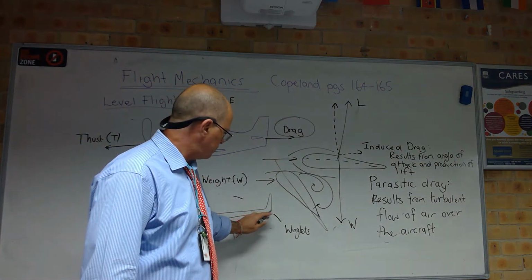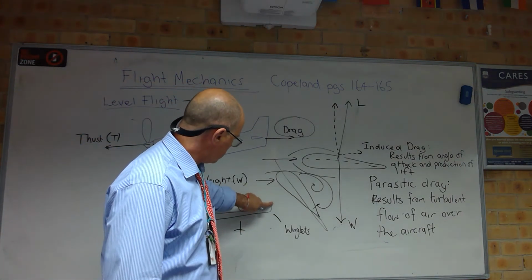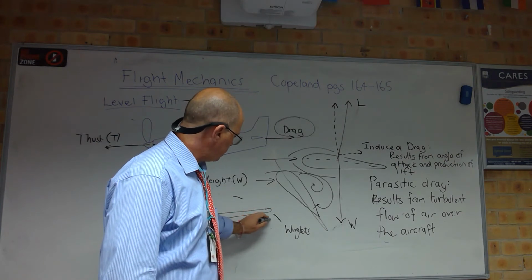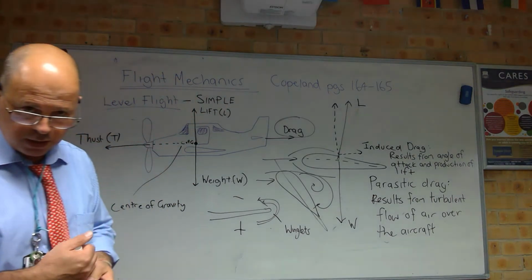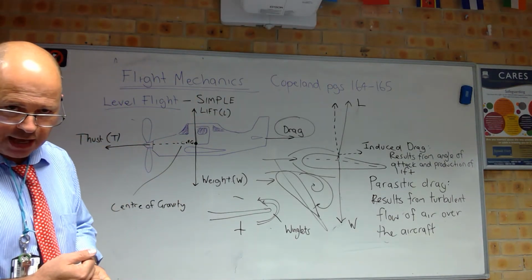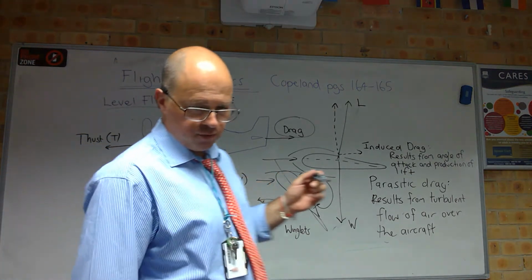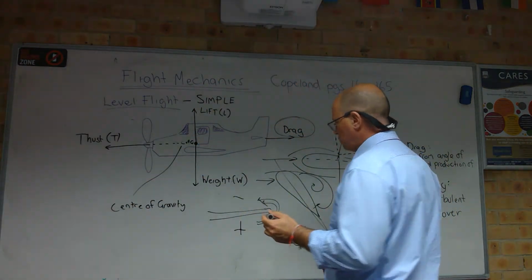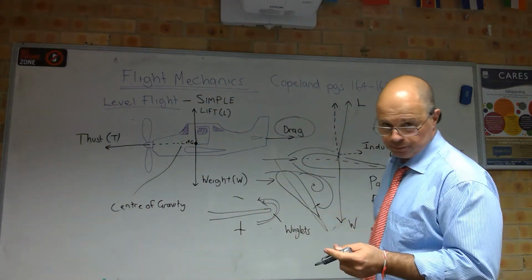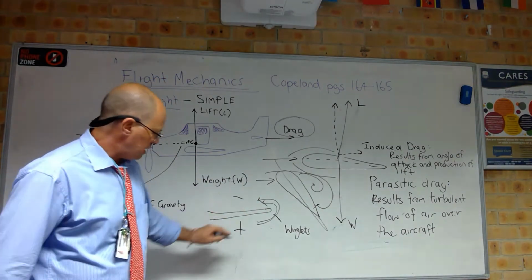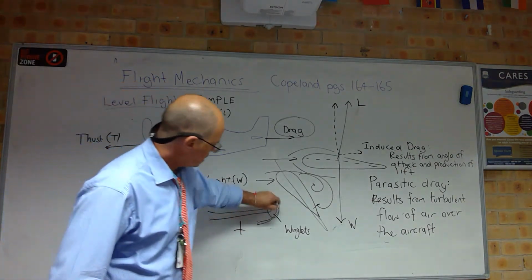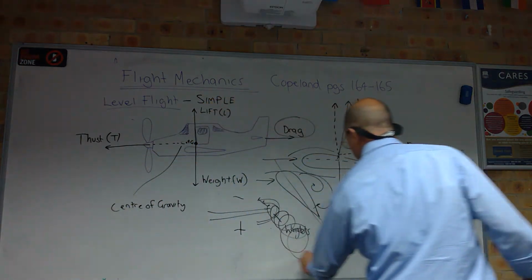So when you get to the edge of the wing, if we don't have this little winglet here, you're going to have air leaking over from the bottom to the top. And you might say, well, what's wrong with that? Well, as the aircraft moves forward through the air, you've probably seen it at the airport. You'll sometimes see coming off the end of the wing a swirling like tornado, okay?